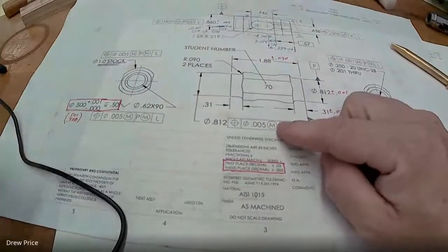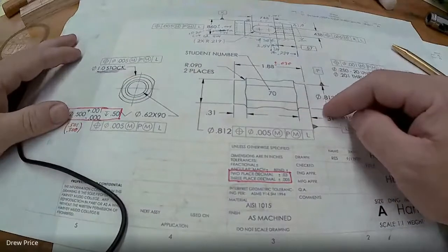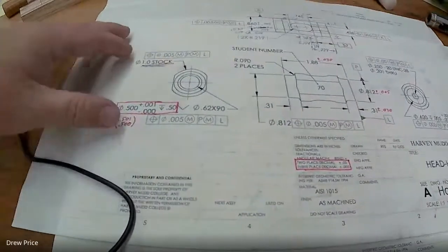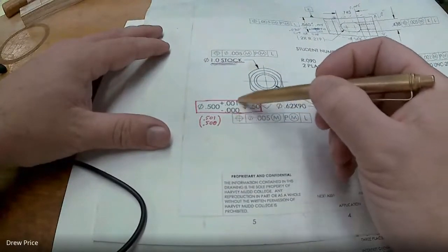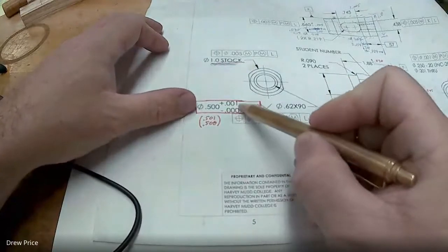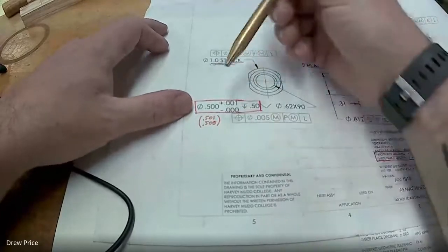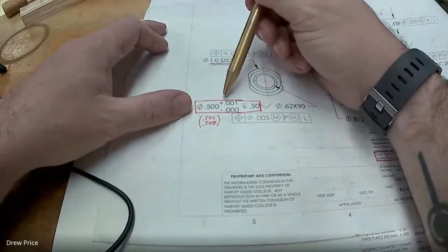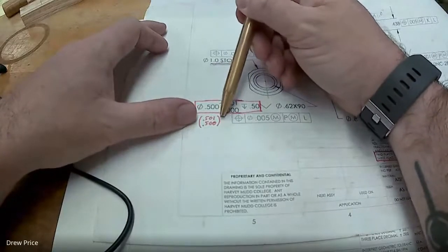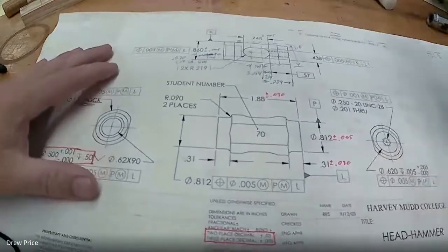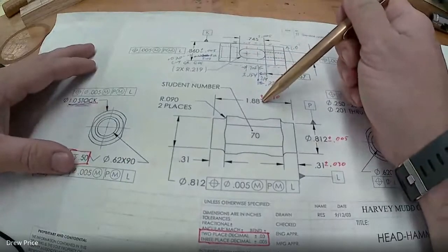And there's two different basic types of tolerance that are shown on this drawing, and they're implicit tolerances and explicit tolerances. So the explicit tolerances are the ones like here, where you have a specific window where the basic dimension is allowed to deviate in either one direction or two directions. So underneath I've written this basic dimension of 0.500 is allowed to be 1,000th larger, but no smaller than this dimension, giving those bounds.